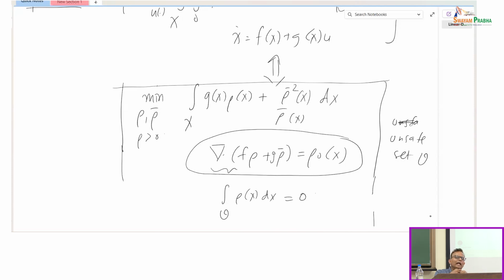Of course, I'll talk about it tomorrow in more detail, but once you consider a density function, then you only need local information of the density function to move forward, because what you end up getting is a feedback controller based on the local gradient of the density function. Because you're only using local gradients, technically speaking you don't really need the global information of the obstacles, as long as you can sense the obstacles well enough.